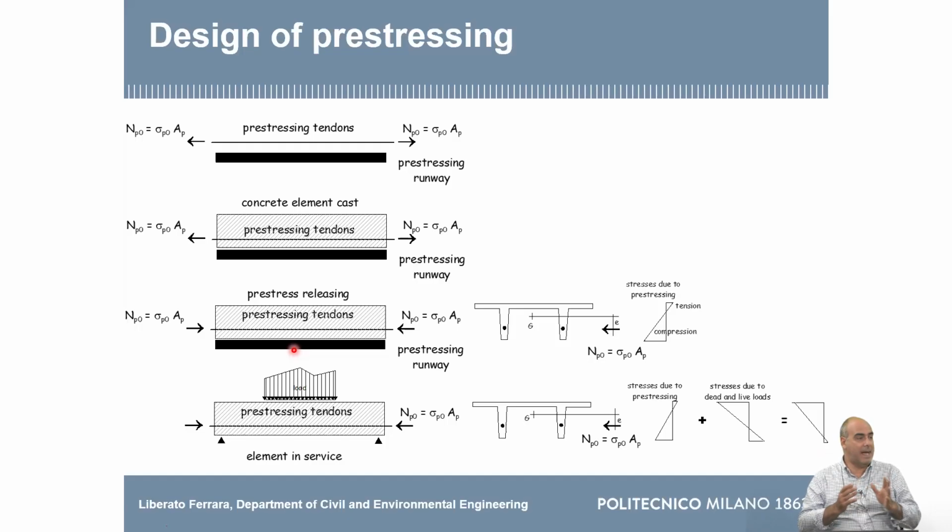Well, when this happens in a factory, you have very severe safety measures in place. Because you can imagine, you can have 30, 40 meters long, even more. Because sometimes you cast several elements in series with the same tendon, and then you cut for the length of the elements. So there are these several tens of meters long cables with quite some tons of force inside them.